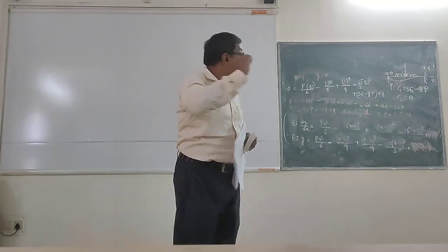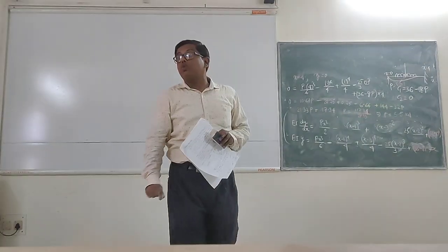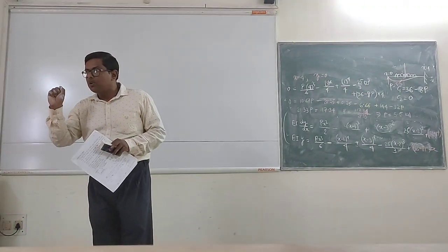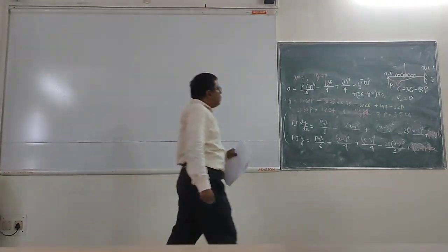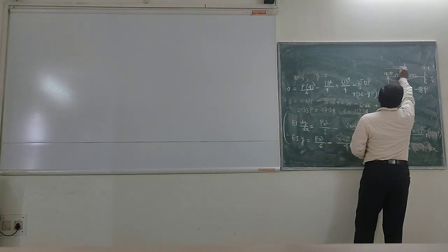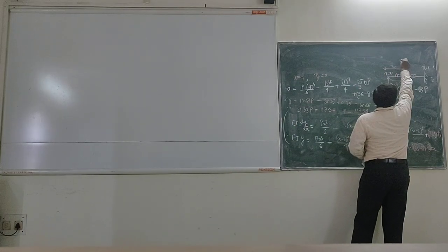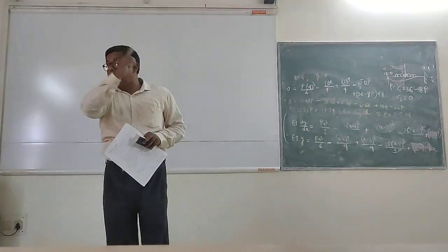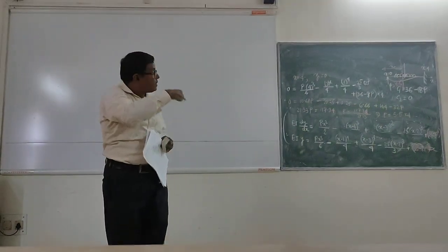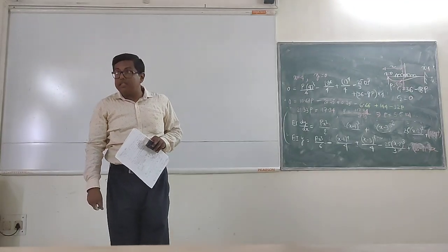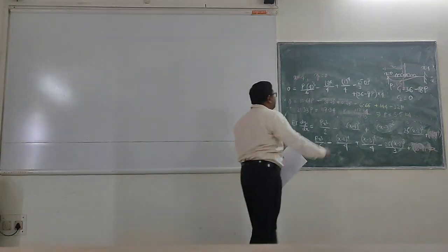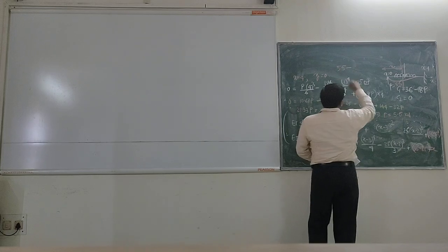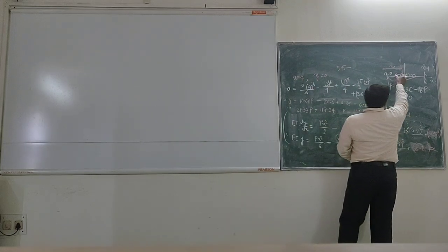Bending moment becomes maximum where the shear force equals 0. So this condition you should apply over here to find the location of maximum bending moment. What is the shear force at a distance x? I will take a section x from here, and this section x should be before the point load. Please try to understand. If I take 5.5 upward as positive, minus, how much will be the shear force due to this?